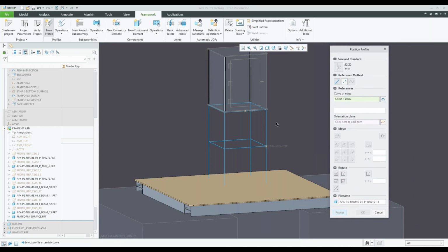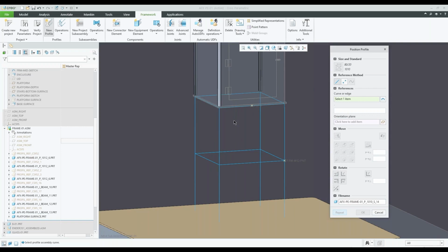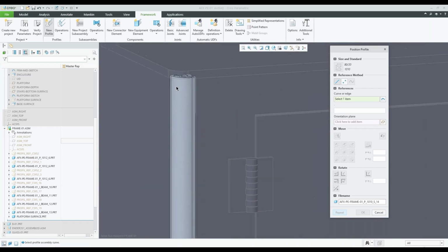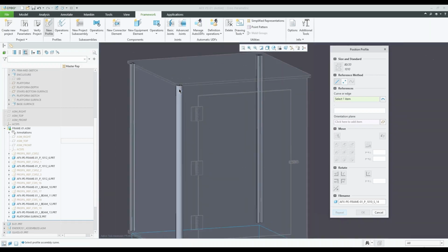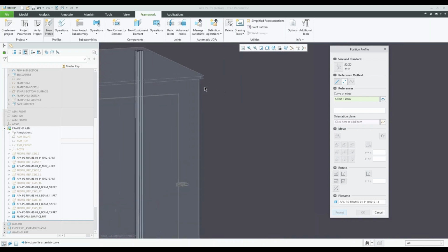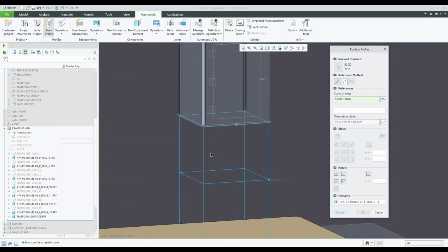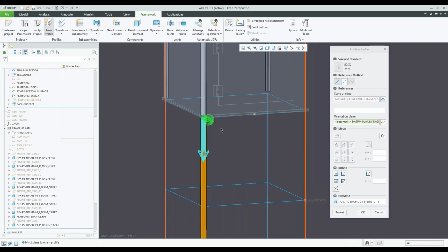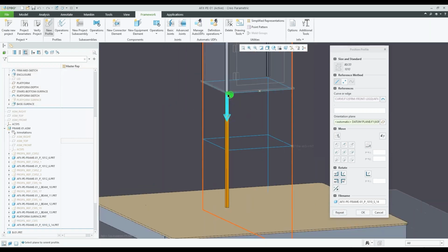The reference method is basically giving me an option here to determine which reference I use to place the geometry. So I can use, in this case, a curve. So I can use a straight edge, right? So up here, you can see I actually assembled this corner profile on an edge of the skeleton surface. And I'll show that later here. So in this case, what I'm gonna do is I'm gonna select this sketch curve from my skeleton model, okay? And it's gonna place it there.